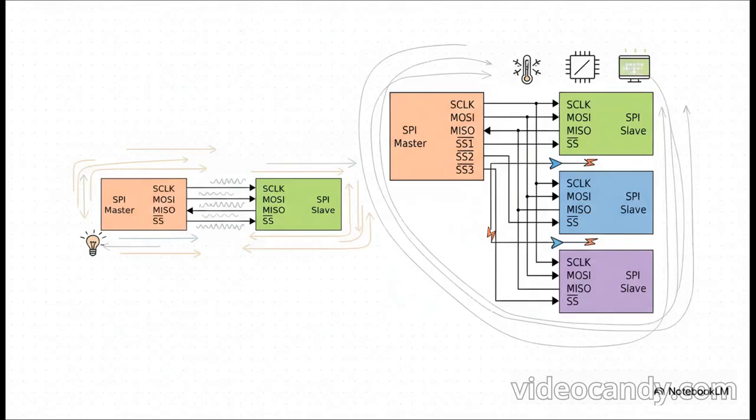The industry is definitely moving towards more inclusive language like leader, follower, or primary, secondary, because the concept is just about one device coordinating the others, not about ownership. And this slide really shows off SPI's flexibility. On the left, you've got a simple one-to-one connection. Easy enough. But on the right, that's where you see its real power. One leader device can talk to multiple follower devices.